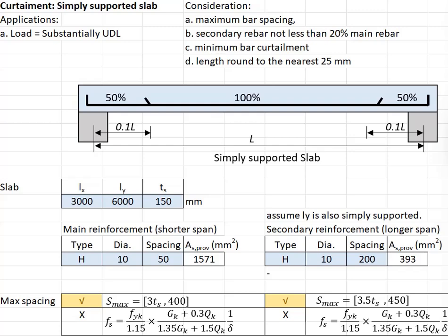However, as the engineers produce the drawing, normally the dimensions are presented in SI unit, which is in mm. As a result, to make it easier for the workers on site, it is recommended to round to the nearest 25 mm so that they can make direct conversions from SI unit to the imperial units.